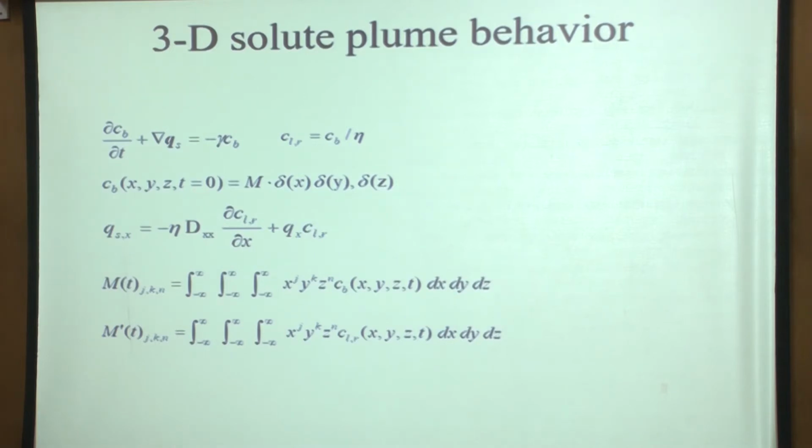dimensions. Okay. And in this case, just as a matter of definition, m prime, this was bulk concentration, this is the liquid resident concentration. In fact, the difference between those two would simply be equal to the porosity if nothing else is happening. Right? If all the solute is only in the mobile solution, then that's how they are related. But this is our definition of spatial moments in higher dimensions.